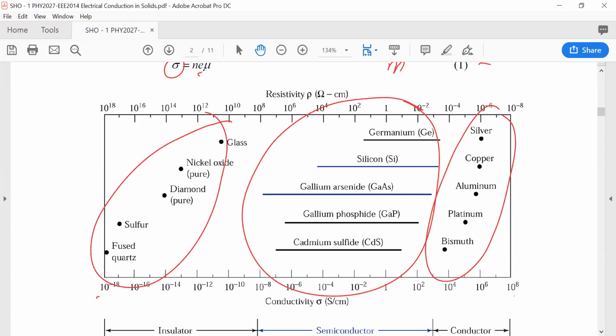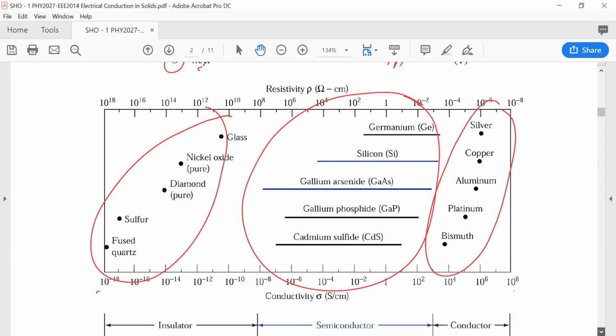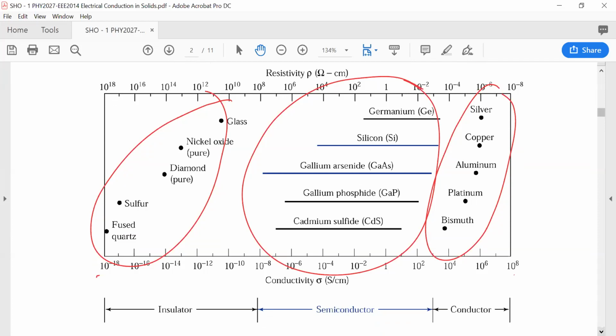This range for each semiconductor arises because of the special ability to vary the conductivity of the semiconductor, and that's done through a process called doping. That's only really possible for semiconductor materials. Okay, and there's your labels: insulator, semiconductor, and conductor. Now, doping changes the carrier concentration, and therefore it changes the conductivity of the material, and it has the largest effect on semiconductors. It's the introduction of impurity atoms to the material, which gives rise to either excess electrons or excess holes compared with the number that you find in intrinsic material.